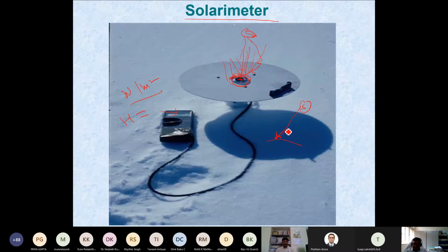At that location and time, you should know everything about this solar radiation, because you know all the details, all the relationships between the earth's position, your position on the earth, and the sun. That is another engineering, and based on that you can determine the direction of the beam radiation reaching our surface, because it is definite; I'm sure it does not change its direction on the way.